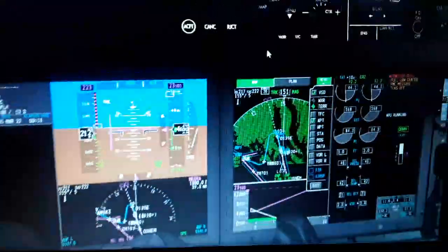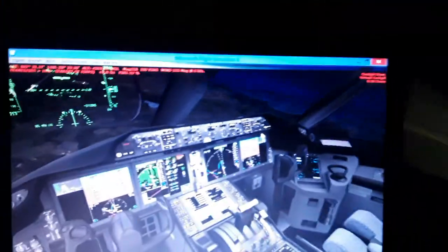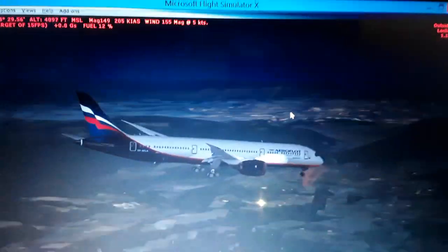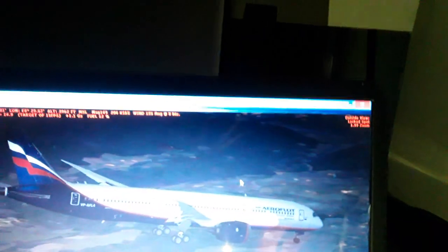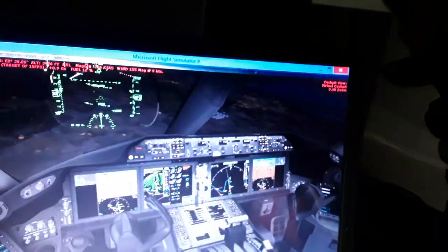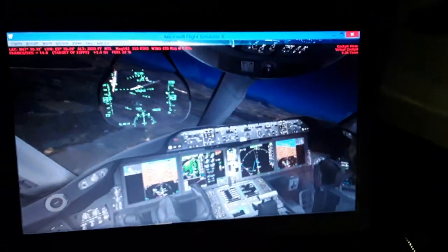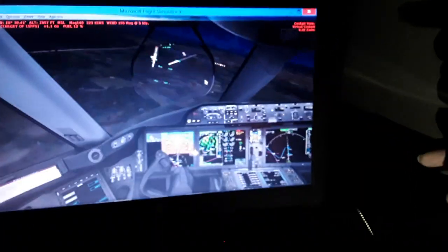You can see the LSZH localizer. We are very close actually to the runway as we are approaching. So we're gonna have also the outside view here. Advance the thrust levers a little bit more. So we need to increase the rate of descent for this approach and landing.